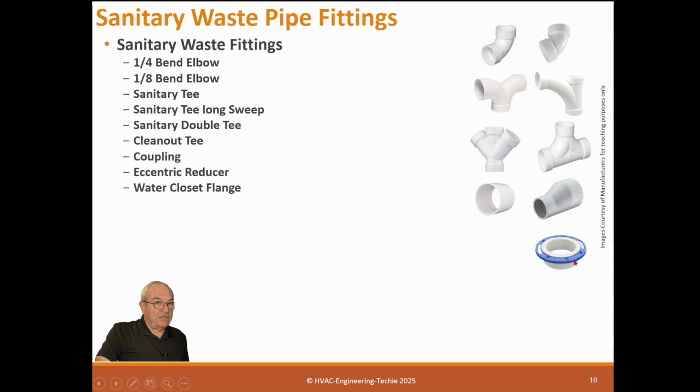Water closet flanges, a special fitting for the bottom of a floor-mounted water closet. And then backwater valves. Again, backwater valves are designed for the case where the sewer line is higher. The top of the sewer manhole is higher than the house, so if there was a clog in the main sewer line, we don't want it to come into the house, so they use backwater valves. This is fairly common. Many municipalities require these. They may even require grinder pumps. It depends what's going on.